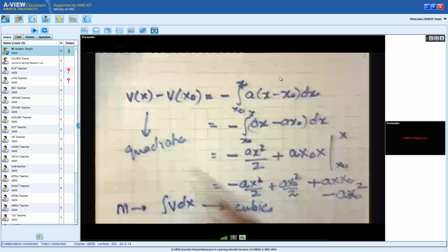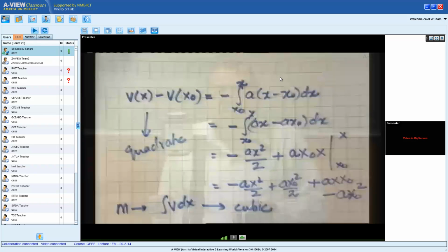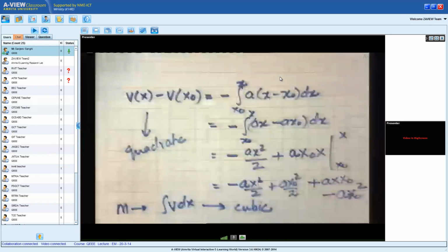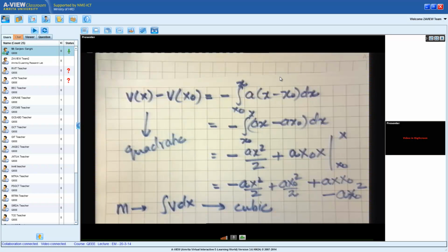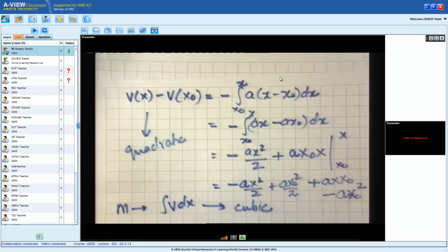But you don't have to bother about integration. You can still use the way which we have done before: we make a cut section, we find the total area under the loading up to the cut section, that will give us P, and we use the same formulas which we have used before. Only thing is, if it's a triangular loading, then the effective force will act at 2/3 from the base, and you use that to find the expression for the bending moment.